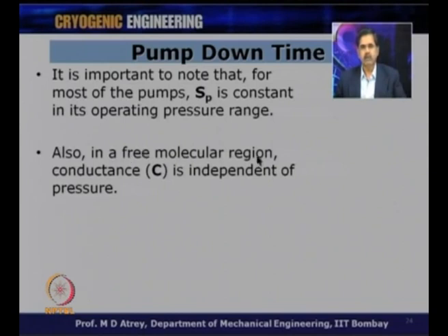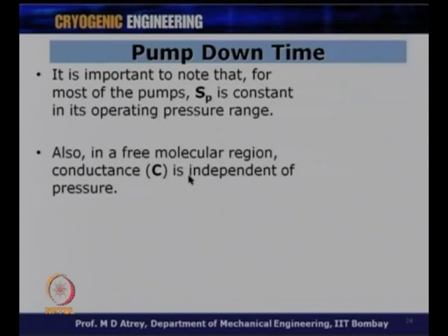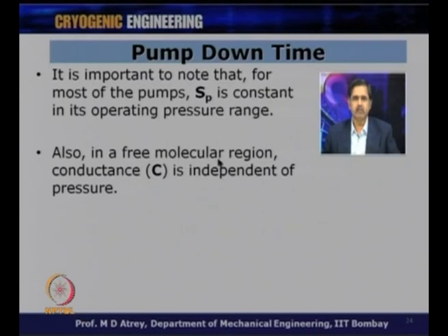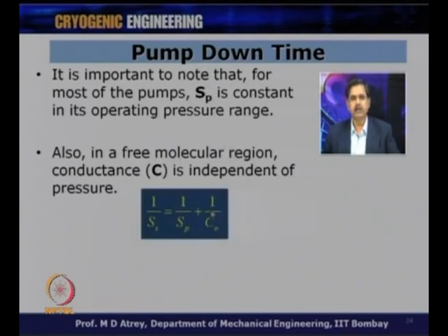Also, in the free molecular region, conductance C is independent of pressure. C depends largely on the gas properties and on the diameter and length, the geometric parameters, of the pipe which connects the vacuum pump to the system. So, I can say again that conductance is also not a function of time. Sp is not a function of time, conductance is not a function of time, and therefore, in this relationship,